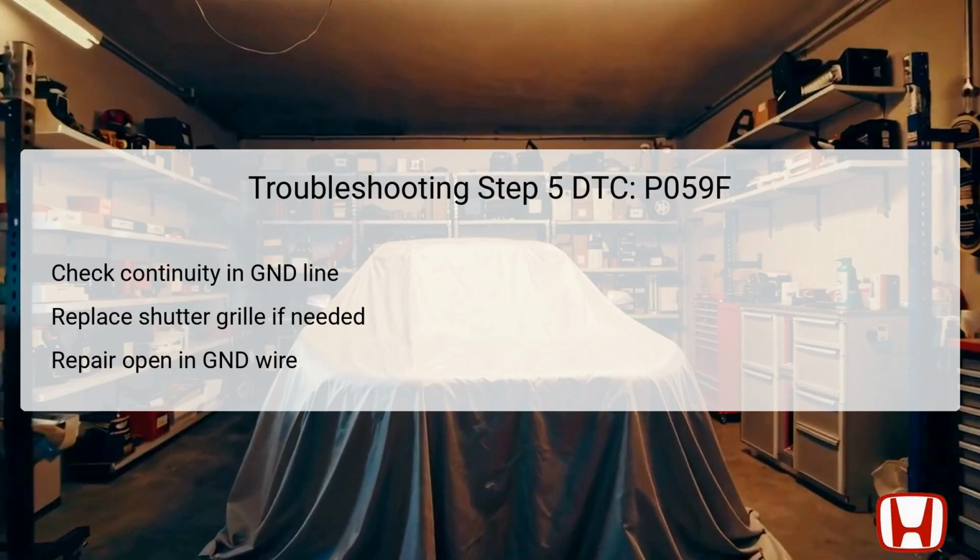to failure. Conversely, if there is no continuity, an open circuit exists in the GND wire, which must be repaired to restore proper functionality. This step is crucial, as a compromised ground can disrupt the performance of the actuator and lead to further electrical malfunctions.